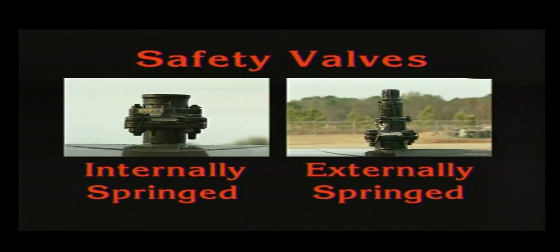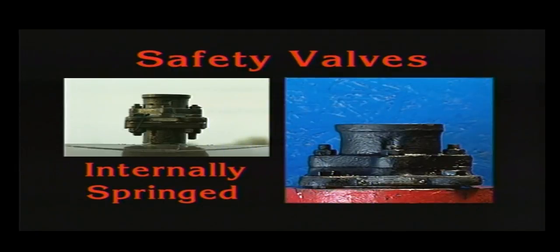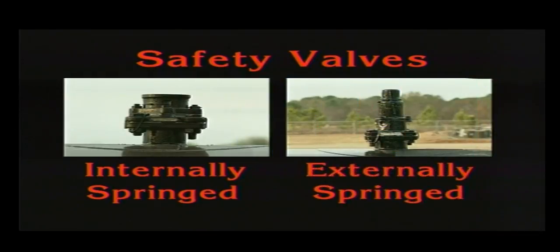Their pressure setting is based on the tank test pressure. As the pressure in the car rises to something higher than the start to discharge pressure, the valve opens and releases pressure to the atmosphere. As the pressure decreases inside the car, the valve closes.